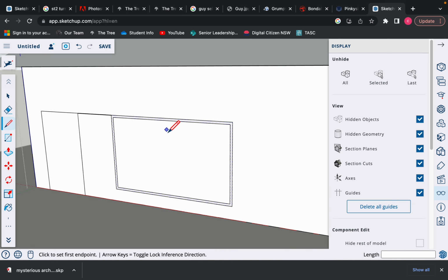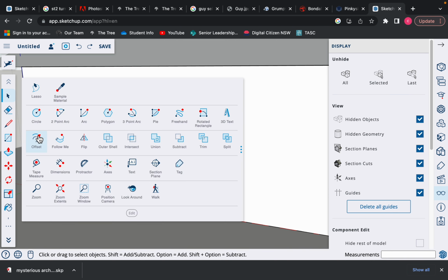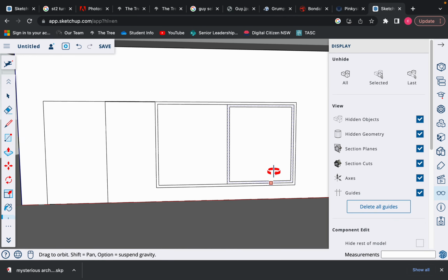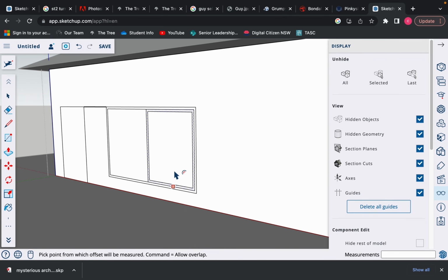And then I might go here through the midpoint, draw this down, and then I might draw the sash of an opening part of my window. So again, I'm going to grab that offset tool and, actually, what I'll do is grab just that panel, which is what I want to go into. I'm going to grab my offset tool and come in and go another 50 mil and that will create the window. Okay, so I've now got a window and door in my structure.